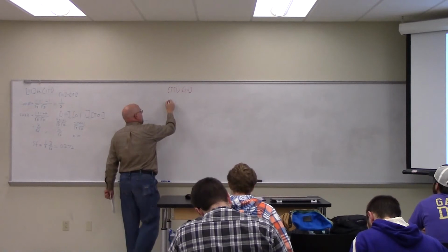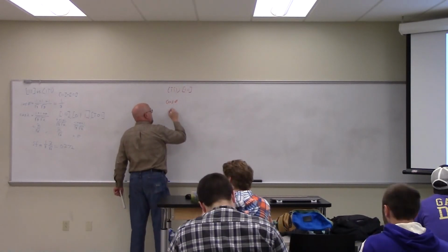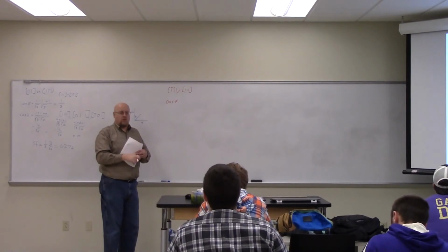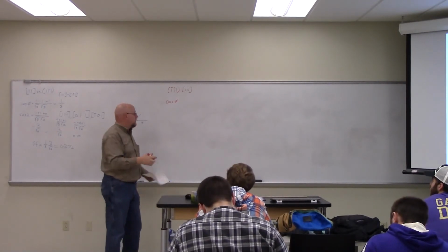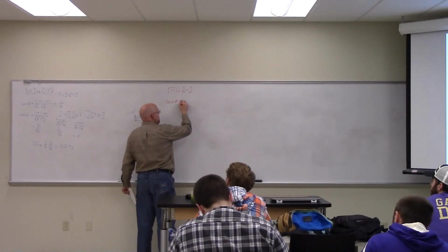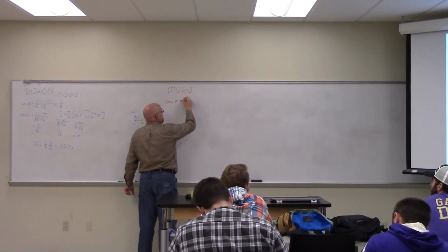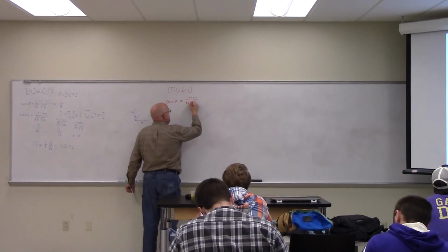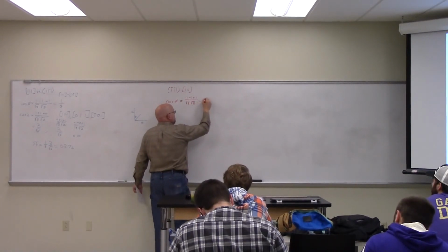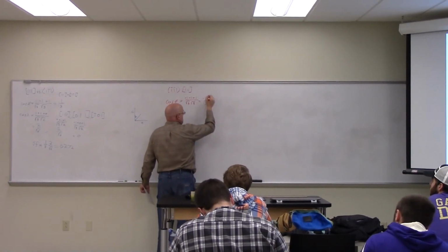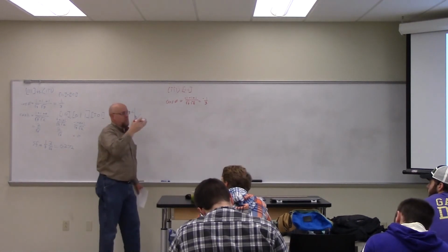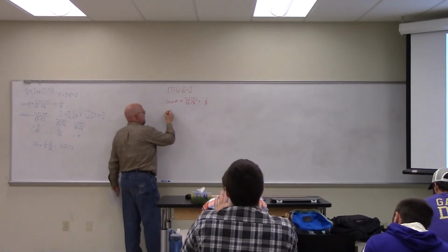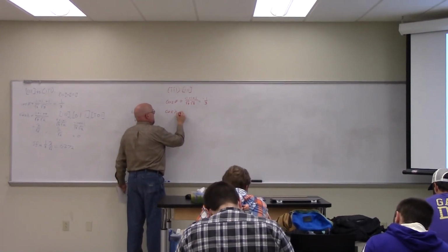Okay, so cosine phi, and you always do the plane first, because if the plane is 0, then it saves you doing all 3 of the directions. We're still pulling in 111. So we end up with -1 plus 1 plus 1 over square root of 3 times square root of 3. That equals 1/3. Actually, -1/3, but that just means we'd be pulling in the opposite orientation. So now we gotta get cosine lambda.